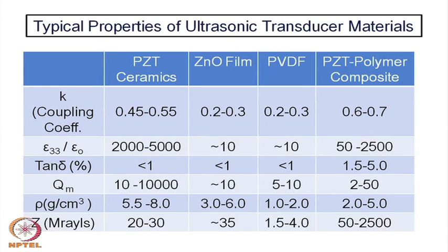This is one we mix. We have talked about PZT polymer composite or ceramic polymer composite for the piezoelectric materials, and in such cases where you need a low impedance and low dielectric constant, you mix up PZT with polymer. So, you make a polymer ceramic composite, and those are very important for the medical diagnostics as well as some of the sonar applications.